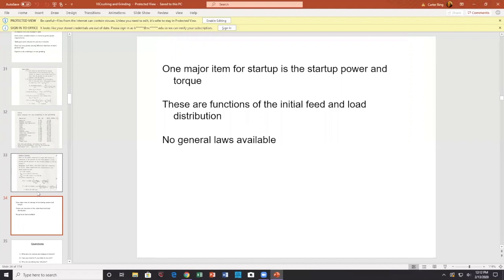Okay, now, when I say you measure power full minus the power empty, that's for continuous operations. However, if you stop your machine and you leave material inside the machine, then the startup torque will be higher as well. Okay, so continuous operation is one value you should be concerned about.